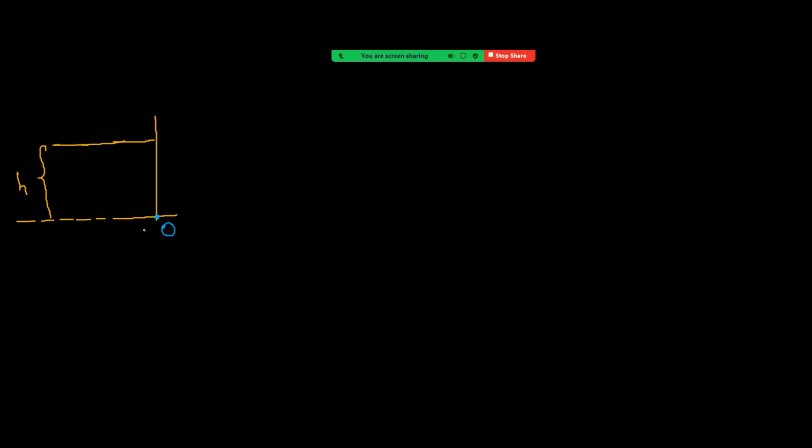Calculate horizontal force. So horizontal force means we can use the result like the entire force acting at its center of mass. So depth will be h by 2. So I'm taking directly that result. Otherwise, we have to use integration at a depth of y, take a strip dy, force acting on that rectangle.